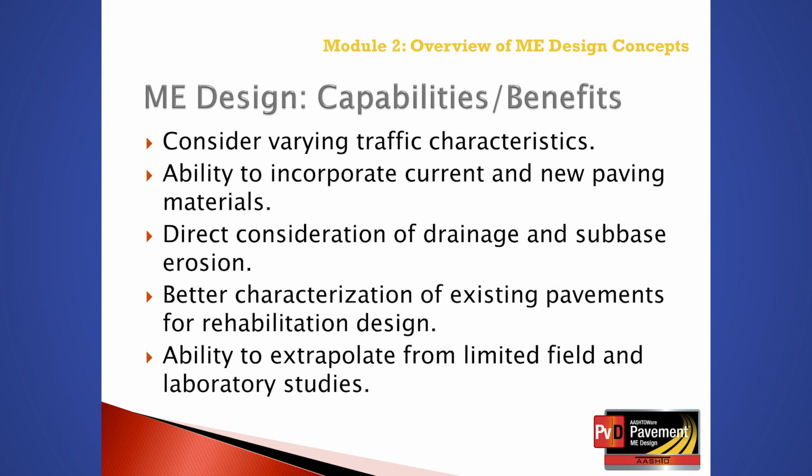Directly consider the impact of drainage on the vertical movement of moisture in the pavement structure for asphalt and rigid pavement design, as well as subbase erosion specific to rigid pavement design. A very important capability is the quantification of the structural condition of the in-place pavement layers for rehabilitation design.